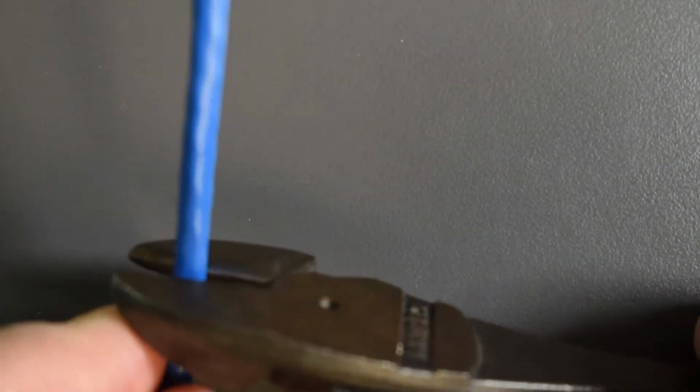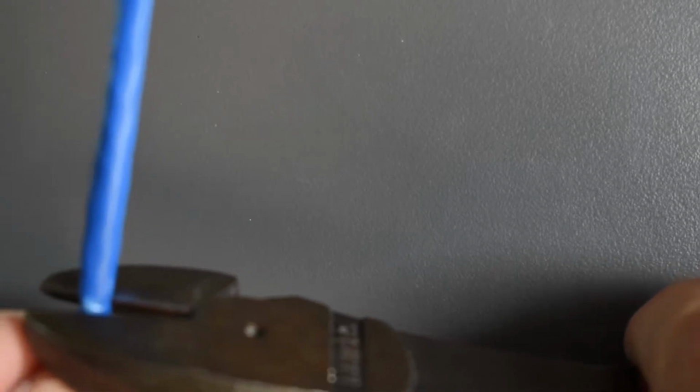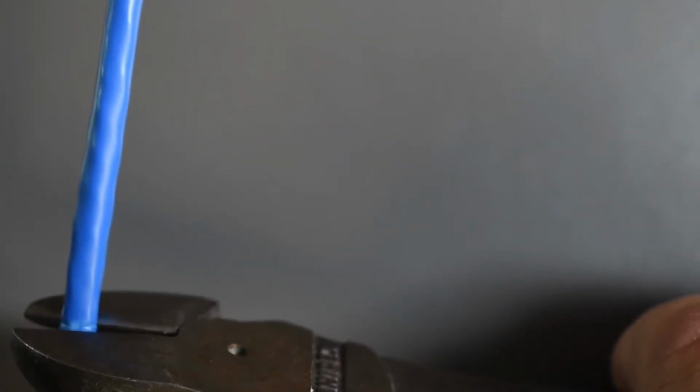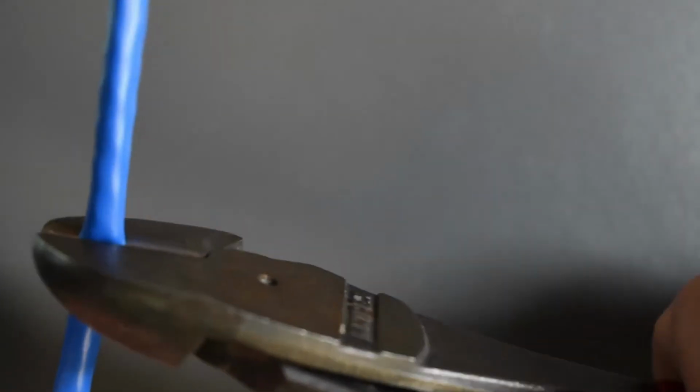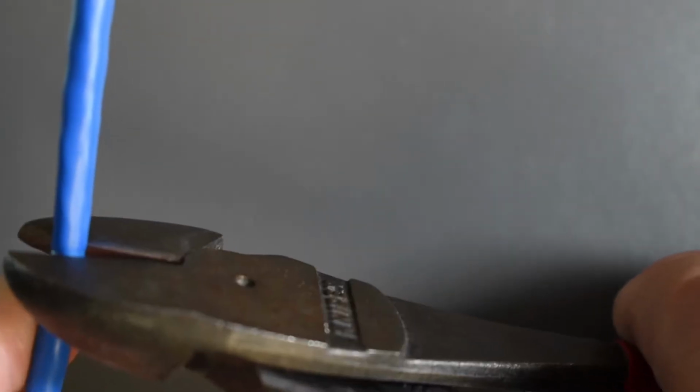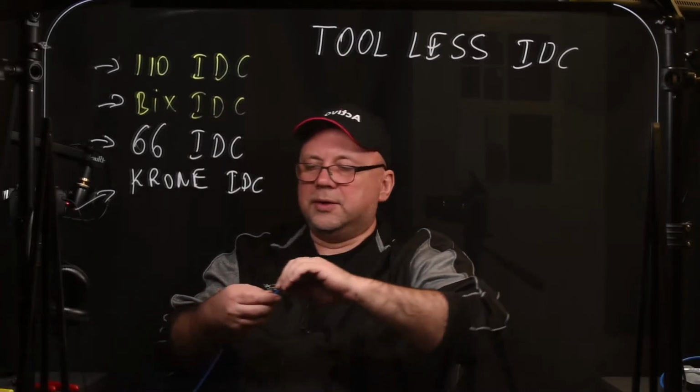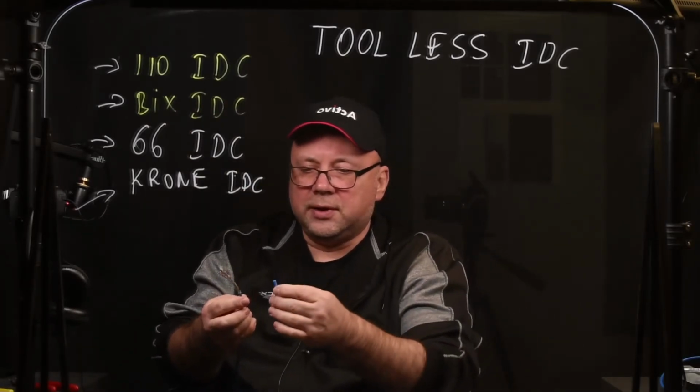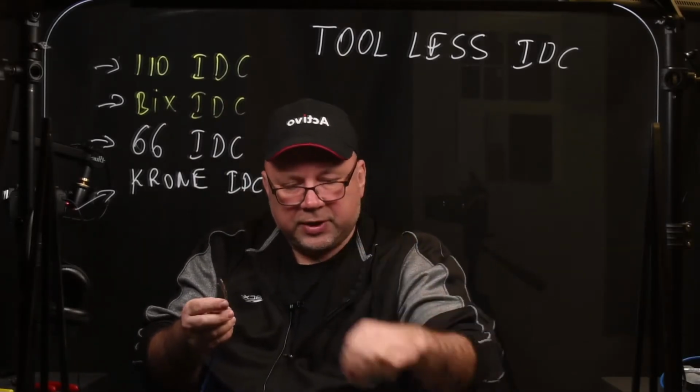Arrange the wire like that, nick it, turn it. So you nick it first and turn it, and you nick it again, right? And that lets you break the insulation and remove that part of the insulation.